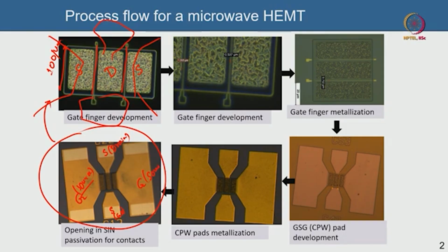Now why am I showing you this? It is because at the heart of it we are talking about RF signals, which are electromagnetic signals, and we are making them propagate in a semiconductor substrate, inside all these metal structures or inside the semiconductor substrate itself. We are making them propagate in a semiconductor wafer. So what we have to talk about are things like transmission lines or waveguides. We have to talk about these things because the electromagnetic wave, which is the RF signal, is going to propagate through these structures. So we call this particular GSG structure a coplanar waveguide, CPW,